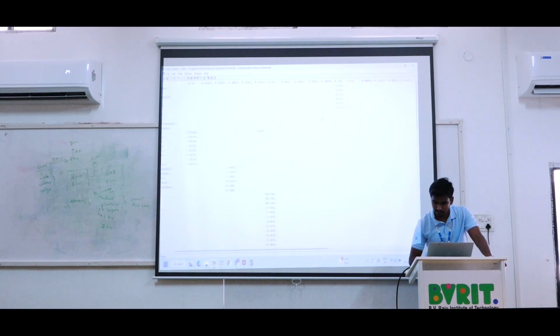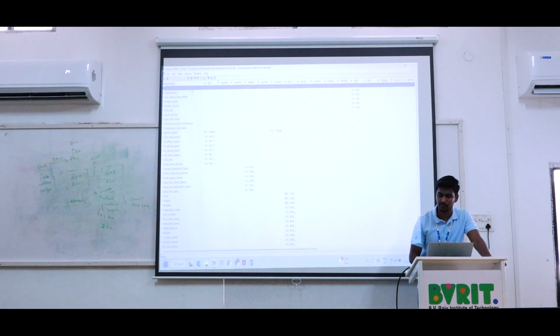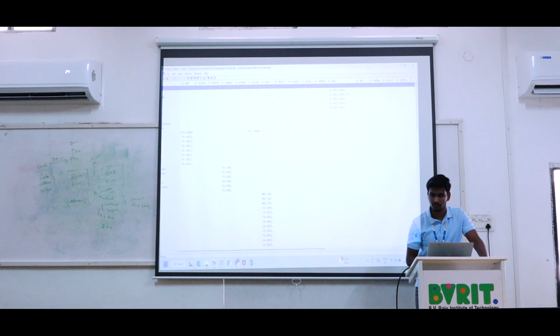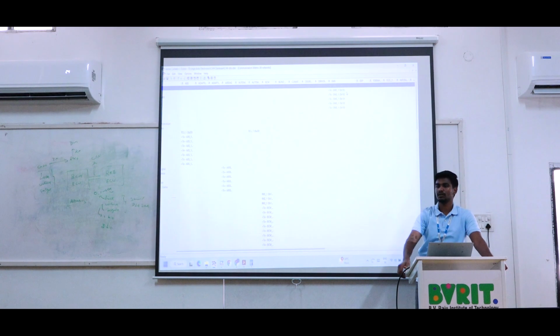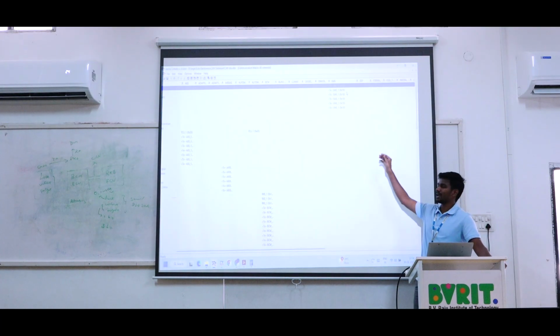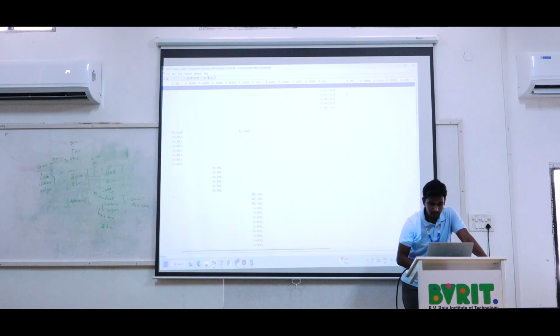So for example, the signal of coolant temperature. The coolant temperature is transmitted by the EMS ECU. EMS means engine management system ECU. It has the ID number 10. The engine ECU is the most important thing in our car, so I am giving it a very low ID number, 10. For any work we need the transmission control unit, chassis system and the engine EMS. These are mandatory. So based on that we will create the ID numbers, 10 and 20. So the engine ECU, the coolant temperature is transmitted by the EMS.